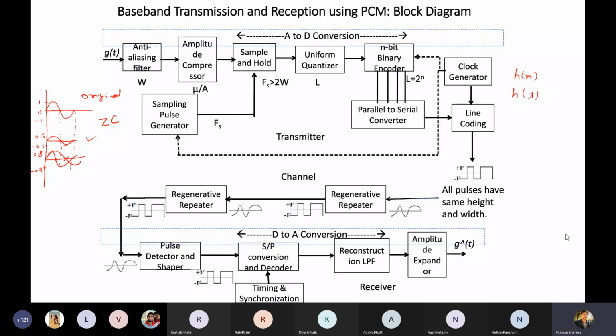So if you are able to identify the impulse response or the system response of the system, means channel in this case, you can undo it by applying the inverse, by feeding the signal to the inverse of your system response. But still there will be a few losses, and one must take care that distortion does not happen.